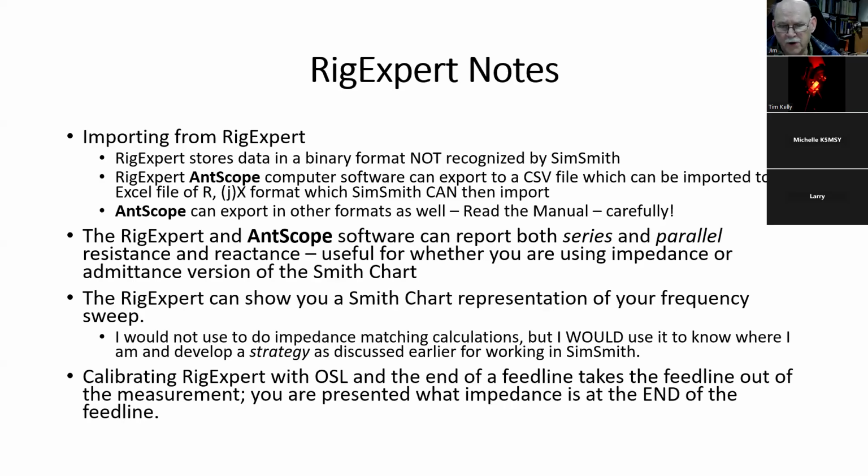The Rig Expert also allows you to calibrate it with what they call an OSL. That's an open short load. And that's a precise device that I have to calibrate my HP network analyzer. It was several $1,000s new. I didn't pay anywhere near that.